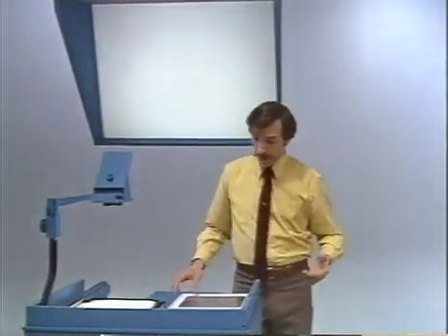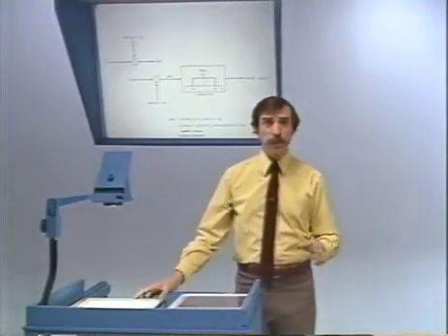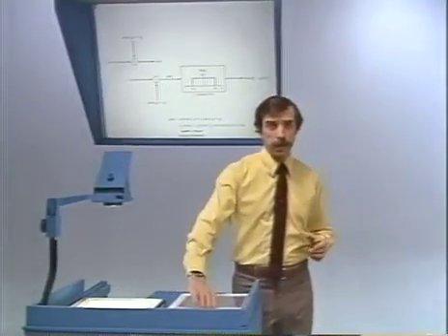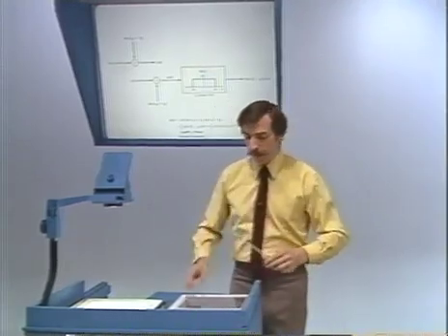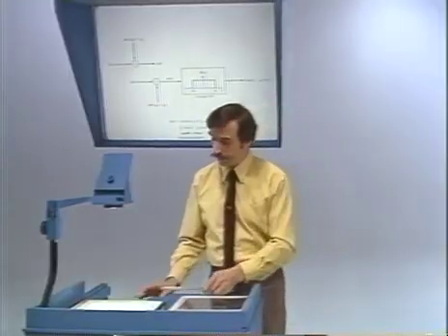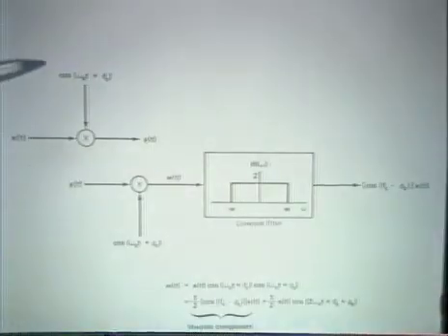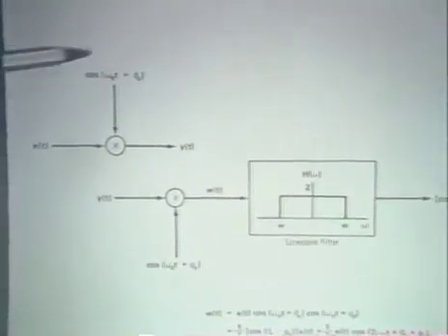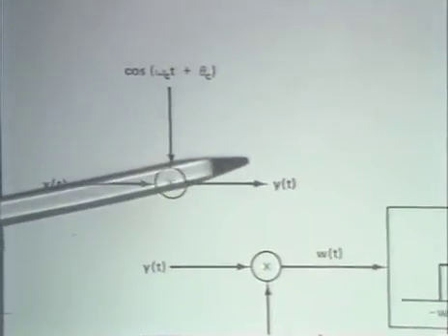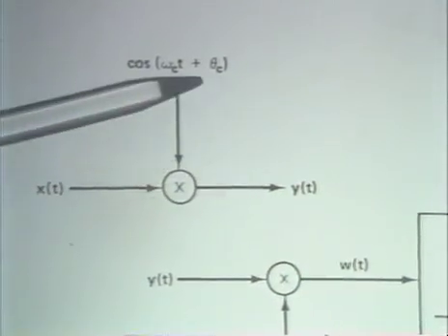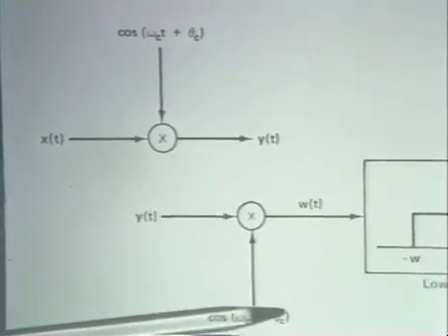And there also, by the way, is another problem, which is the issue of synchronization in frequency. That's examined more in the text, and what I'll focus on here is just the issue of synchronization in phase, to give you some sense of what the issue is. Okay, so now what we want to look at is what happens if we have a modulator with phase theta sub c and a demodulator where the phase, instead of being theta sub c, is some other phase phi sub c.